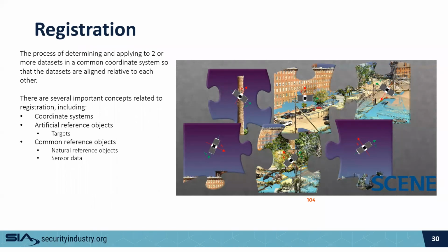There is also the process of placing physical targets, using a total station to measure specific targets, or using an RTK network, real-time kinematic, to tie into an existing GPS system and add controls.